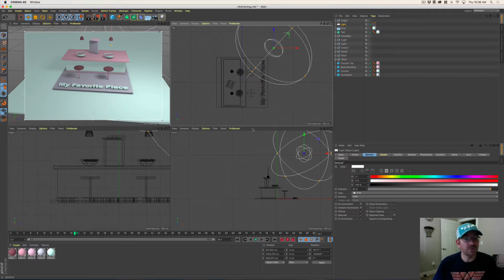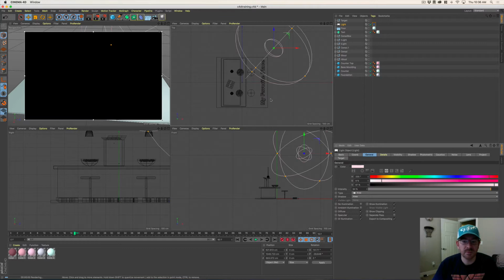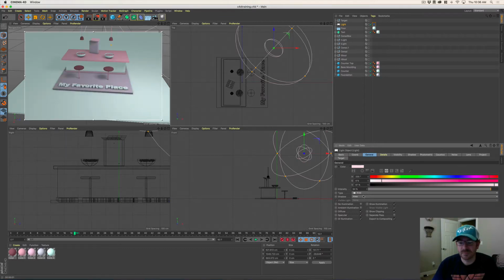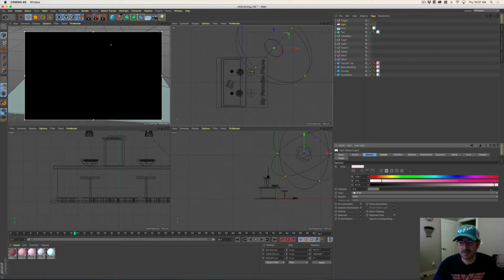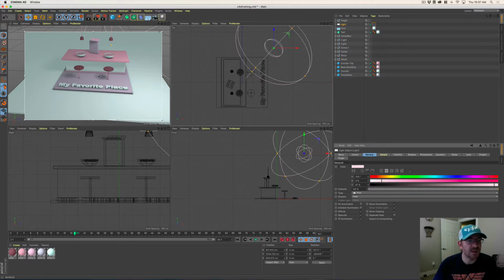You can also add a color to your light. I would suggest something really subtle and something that is in your scene. So I like this pink here. I'll bring that up. So kind of a pinkish hue. Maybe just 100%. All right, you see some nice shadows being cast from the stools. Once you get that light figured out, it's already targeted, it's already ready to go.